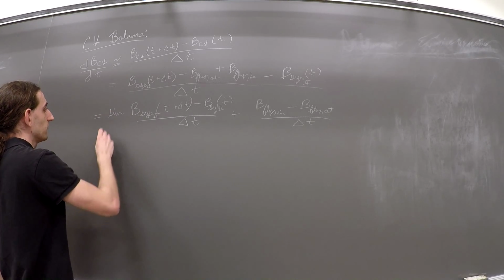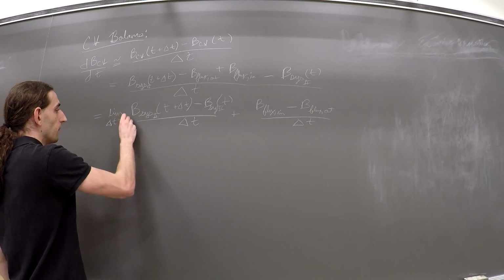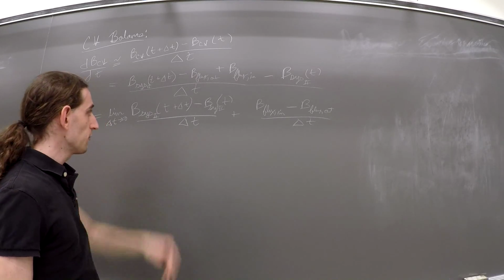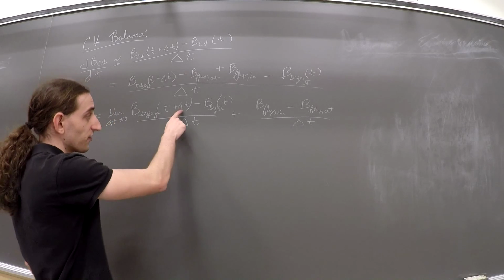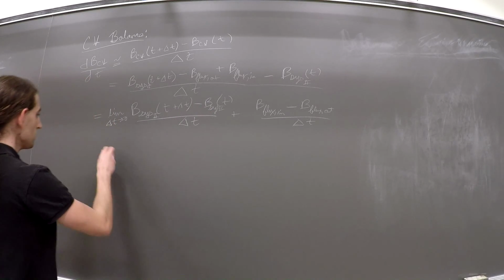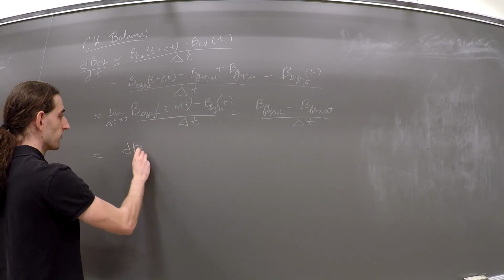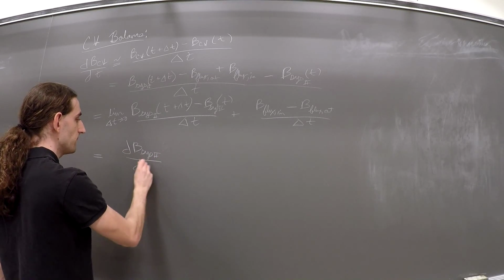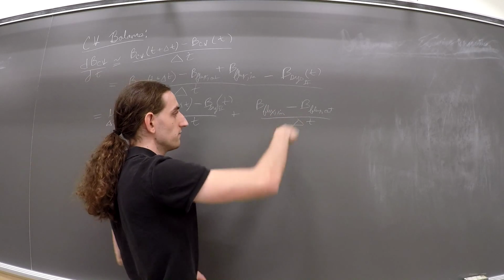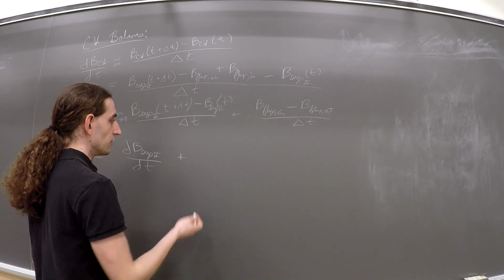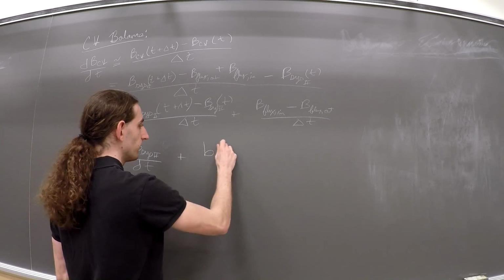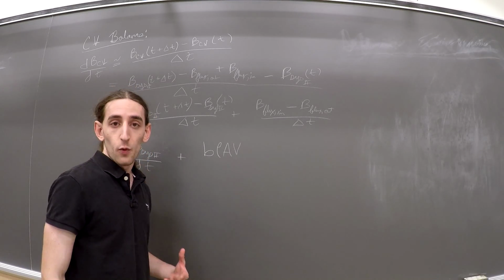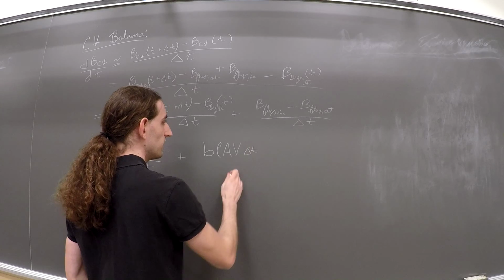So we're going to take the limit as delta t approaches 0. And this is the definition of a derivative, right? We're taking the infinitesimal change with a very small delta t of this property. So that allows us to write the derivative of system 2 with respect to time. And we can plug these terms in. So basically we have our extensive property times rho A V, where V is our velocity. It's not to be confused with volume. And we have our delta t.